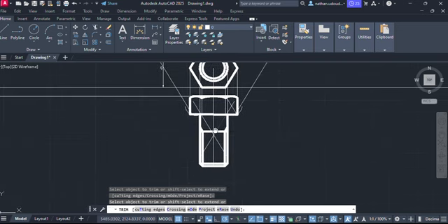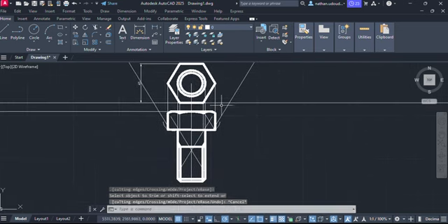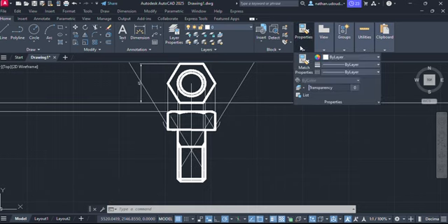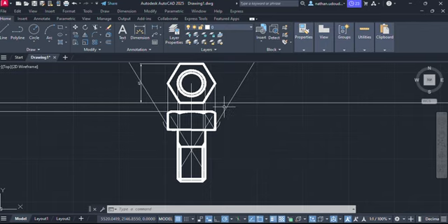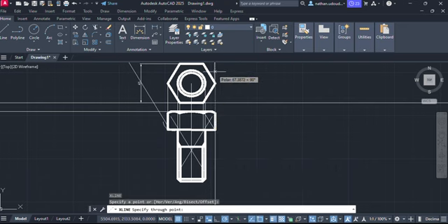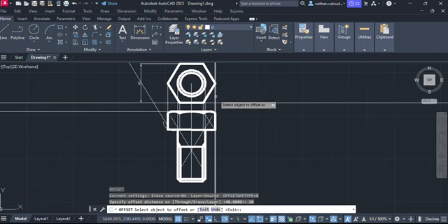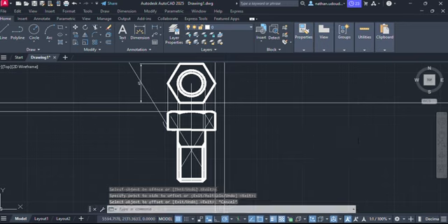So now that is that. So now that we are done with the front elevation, we now move to the side elevation. But meanwhile, you can also delete it. So offset, you can take XL, enter, that's your vertical line, and then offset to the right by 10. So now this one is to the right by 10.